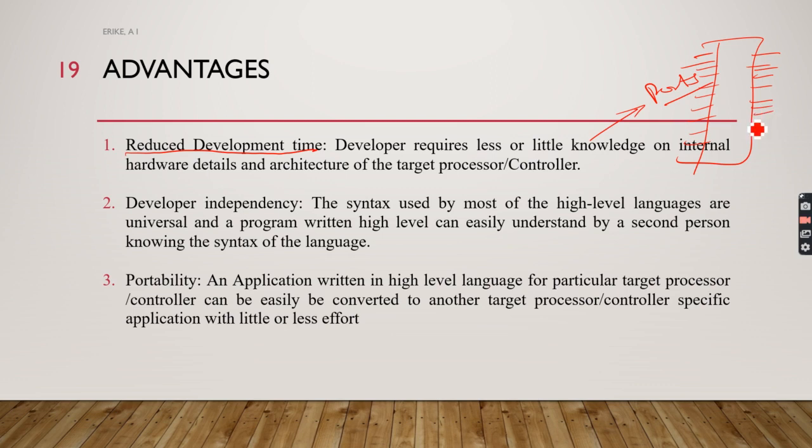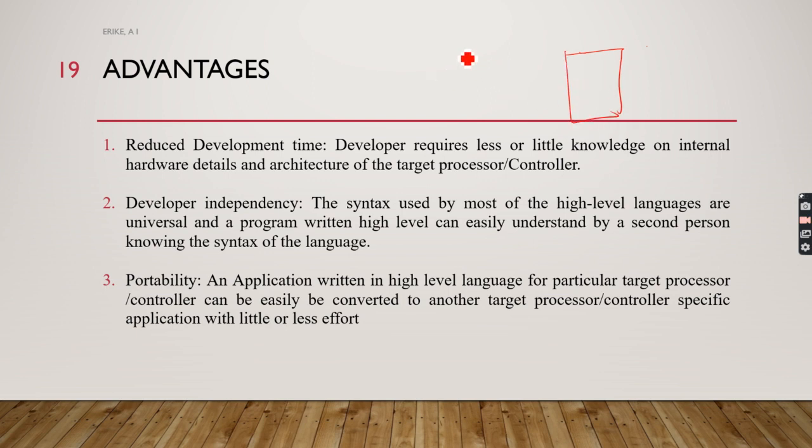where you can say send high here or send low there. The basic program that we'll be writing is, if we want to connect a switch, we can use a pull-up resistor. Connect this other one to ground.